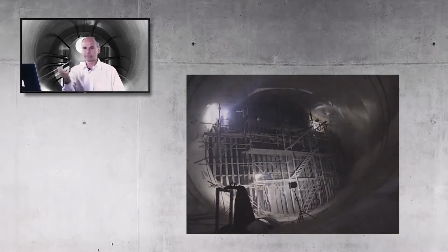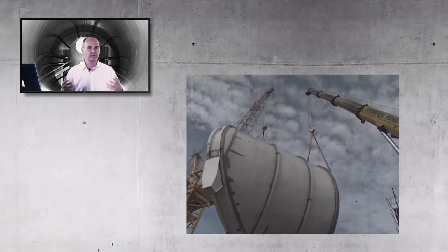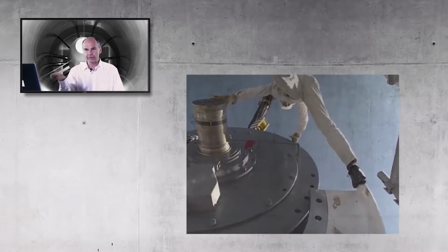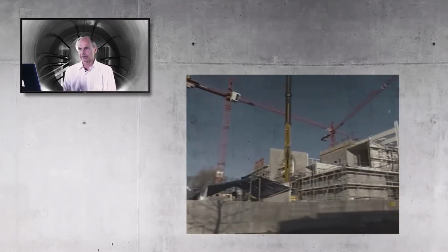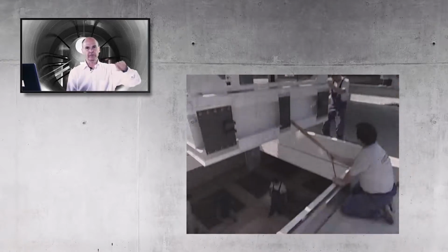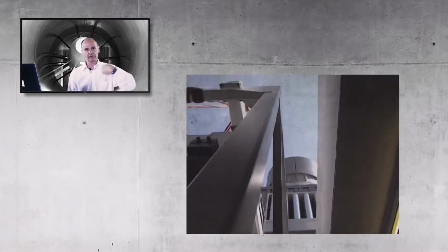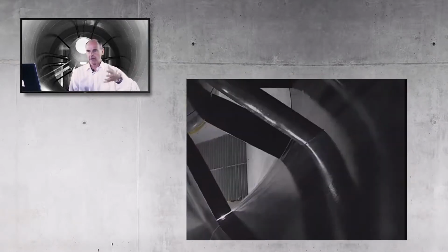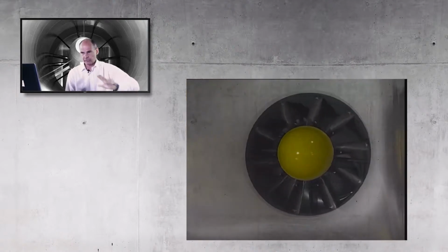So just the science of building a wind tunnel in itself is interesting if you're an engineer. And then going a little bit more into the aerodynamic side of the design of a wind tunnel, if we start with the fan, it blows the air along, and it creates turbulence. A fan will tend to take the air and make it rotate because you're rotating the fan blade. So the fan blades are designed to push the air in one direction, but they add some rotation. So after the fan, we have anti-rotation vanes that try to re-straighten the flow.